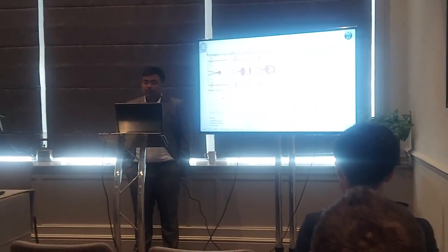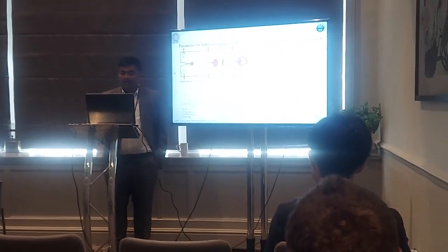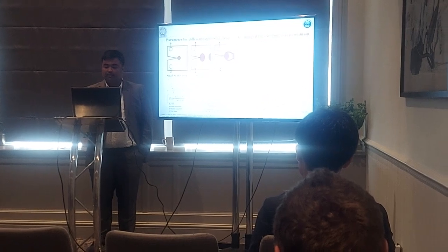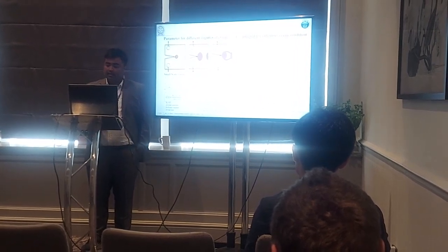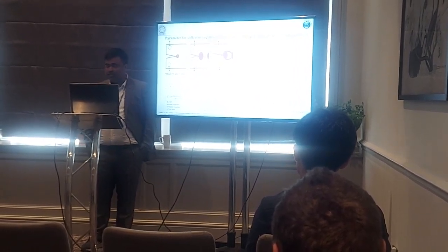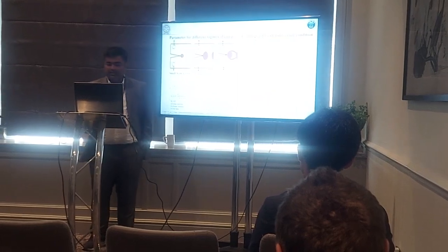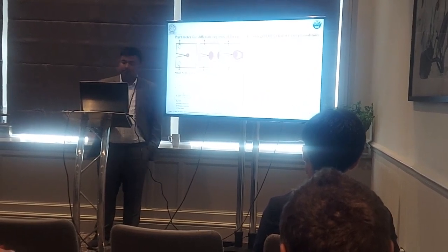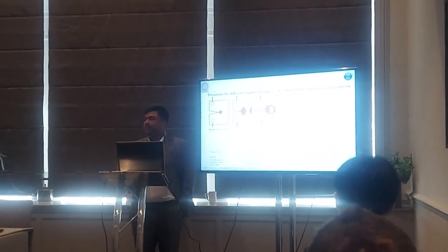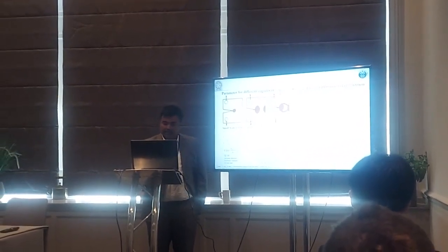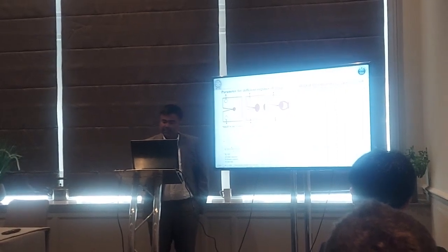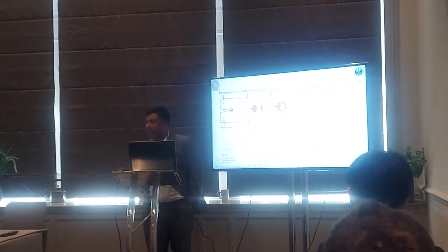For this condition, it comes from the Ramberg-Osgood relation expression, where n is the strain hardening exponent, and when this condition is valid, then we can apply the J integral. And here phi is the strain energy density.